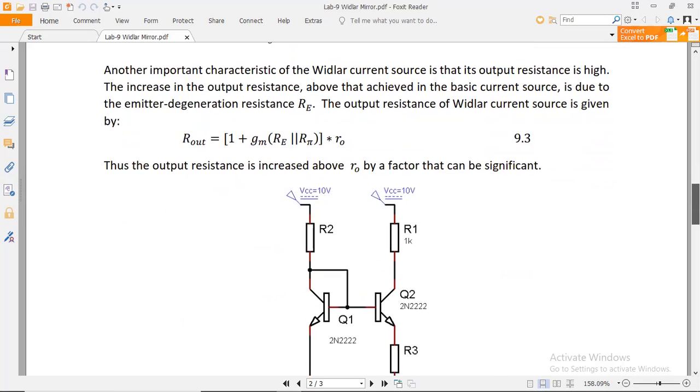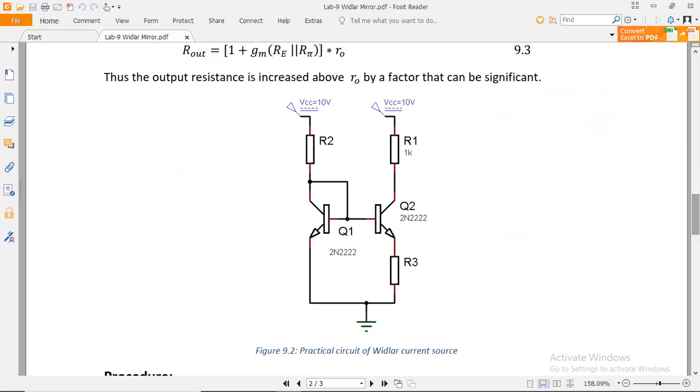Here is the complete circuit of today's lab that I have already built in Multisim simulation. There is a 10 volt supply, R1 and R2 with their resistances, and two BJT transistors. The bases are driven by the source through the resistance, and Q2 is connected through a resistance to ground while Q1 is connected directly to ground. This resistance is connected to vary and limit the current on the Q2 side, and the Q1 side goes to ground without a limit.